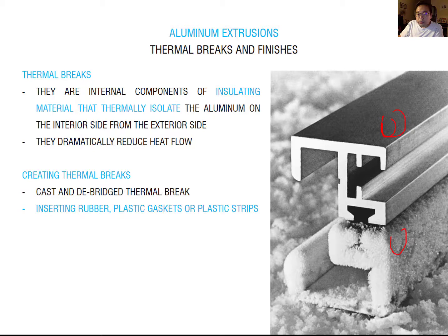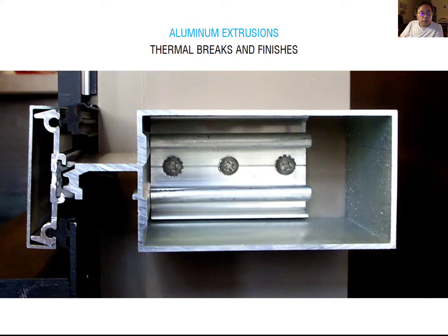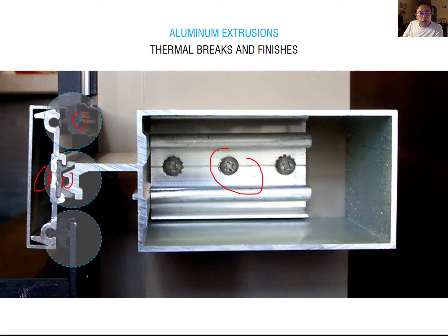They use the rubber gasket here. The rubber is a very low conductivity material. That's why heat energy never transfers through this low conductivity material. So you can totally separate the inside frame and outside frame, but they are still connected by this low conductivity material, which is the rubber gasket. Nowadays we highly recommend using the thermal break window frame rather than just a single piece design, because it has much better thermal performance. You can consider this image. You can see outside and inside. You can use the three rubber gaskets here. It means it is totally separated from outside and inside through this low conductivity material.